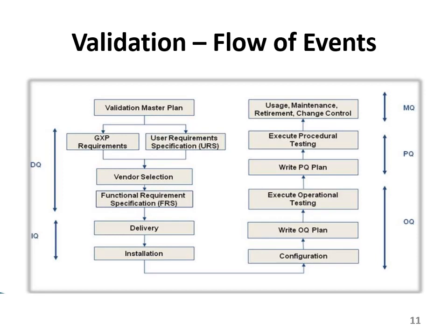After installation, OQ, that is operational qualification, where you start the operation of your machine. So configuration: after installation, you have configured everything, that everything is okay and you are settled with the machine or equipment, and then write the OQ plan, how to operate it. Write it down. It will be not only easy, but better for the machine, for yourself, and for the process, all the things.